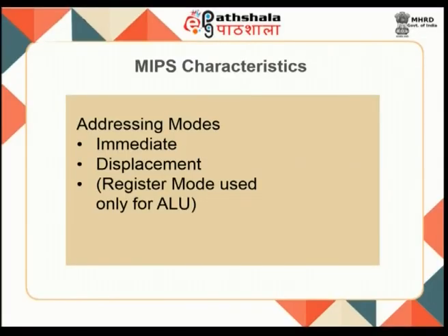And if you look at the addressing modes, there are only 3 addressing modes supported. You have immediate addressing, you have displacement addressing used for load and store instructions for memory related operations, and it uses a register mode or register addressing for ALU operations. Recall that the MIPS architecture is a load store architecture or a register ISA, where all arithmetic operations can be done only on register operands, and load and store are the only instructions which can involve memory operands.